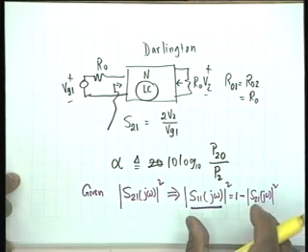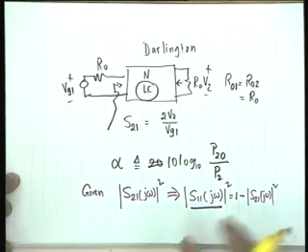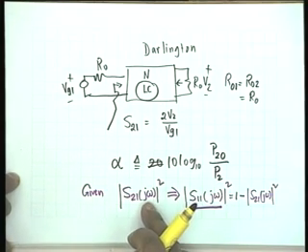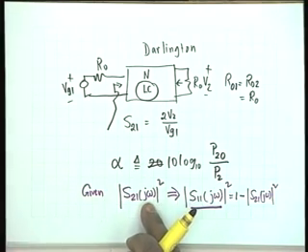You see, this particular step is a very, very elegant, very beautiful step. What it does is the transfer function synthesis problem. S21(jω) after all is a transfer function, right? It relates the voltage at one port to the voltage at some other port.